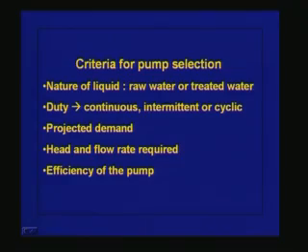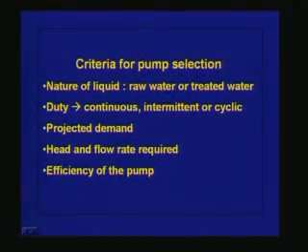That nature of liquid is an important parameter in the selection of the type of pump. Then the operation of the pump, or what we call the duty, whether we are going to operate this pump continuously or intermittently or in a cyclic fashion. So pump selection depends upon that factor also.